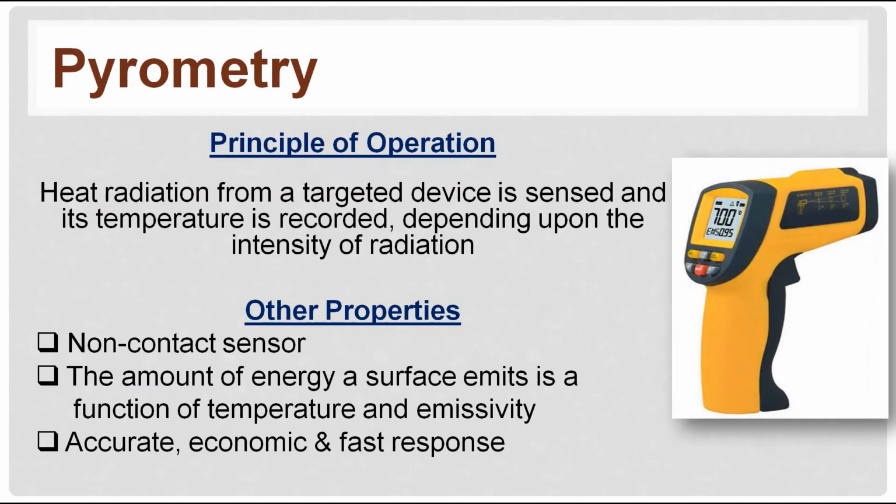Pyrometers are used to measure heat emitted by an object. Radiation is emitted by every object when it is hot. This radiation is referred to as infrared because majority of the radiation falls within the region above the visible red light in the electromagnetic spectrum. Radiated energy is useful in determining temperature of the body being measured. This heat energy is received by a detecting device and transformed into electric signals.